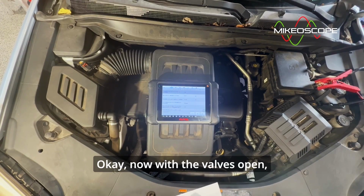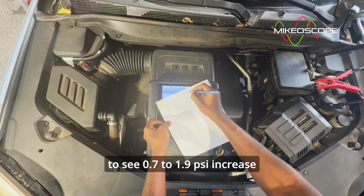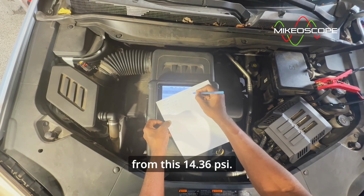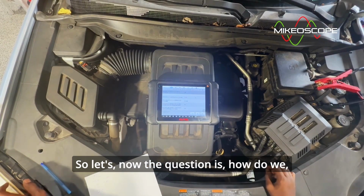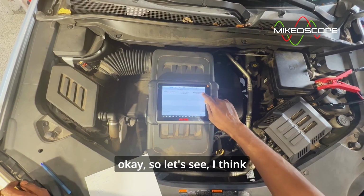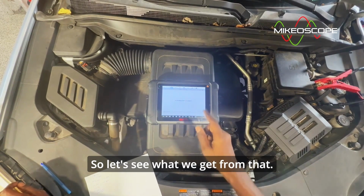Okay. Now with the valves open, we expect to see, let me write here so you guys can see. With valves open, we expect to see 0.7 to 1.9 psi increase from this 14.36 psi in the off state, okay? So now the question is, how do we open the valves? Let's see. I think the secondary injection system activation will open the valves and turn the pump on at the same time. So let's see what we get from that.